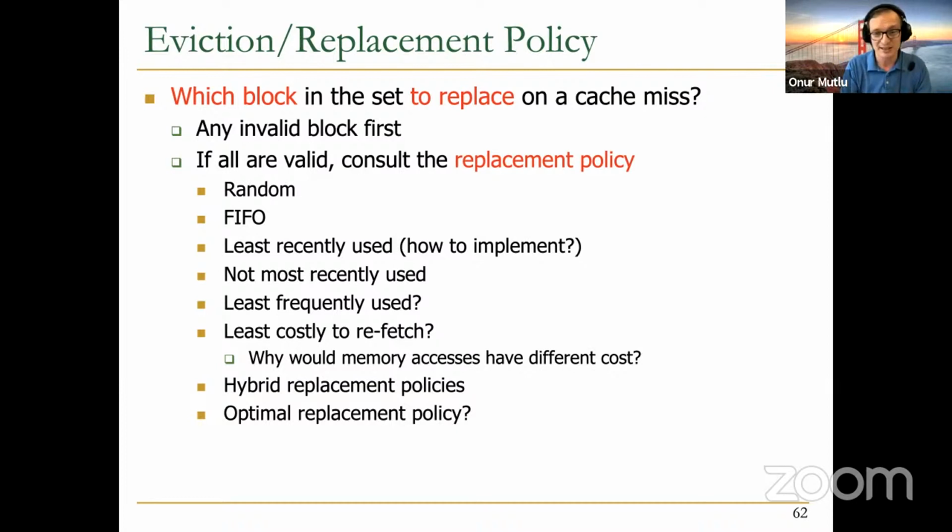In a multiprocessor, two different processors may be caching the same location, and one processor may write to the location, which makes the other processor's cache stale, which means that when this other processor is writing to its own cache, it should invalidate the other cache. That's one way of designing cache coherency. So yes, usually valid bits are also needed for the cache coherency protocol. In fact, modern cache coherency protocols require even more bits than the valid bits. They require more like 2 or 3 or 4 bits in existing cache coherency protocols. So that's a very good question.